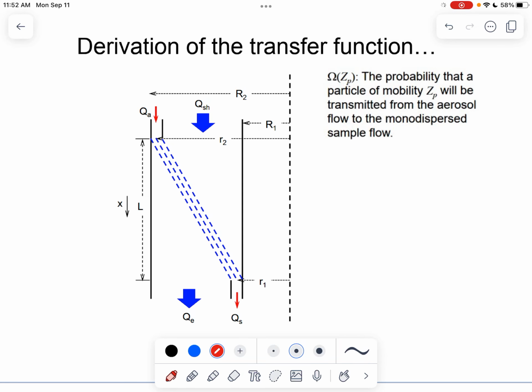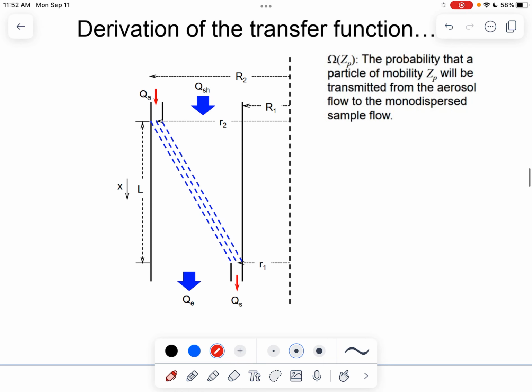And then in terms of converting the CPC reading to the number concentration, it is going to be a little bit more complicated, right? So we mentioned that the particles can carry multiple charges, which means that the concentration we receive downstream of the aerosol outlet is going to be particles of different sizes with different charges. Now let's just start with a simple scenario again. Let's assume that the selected particles carry one charge only.